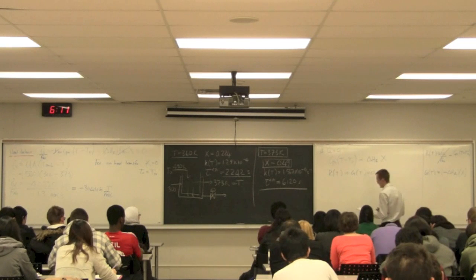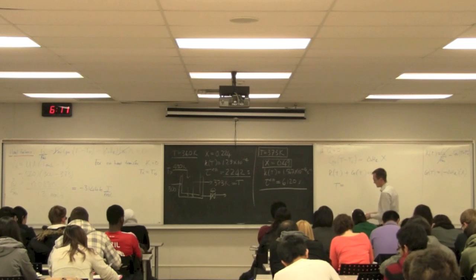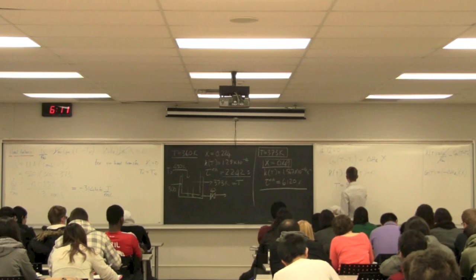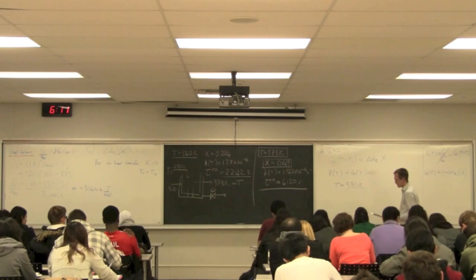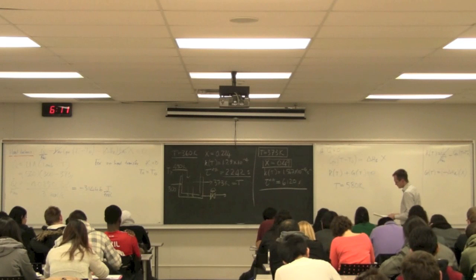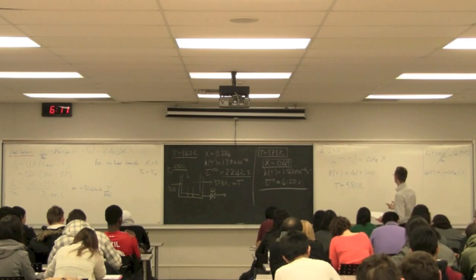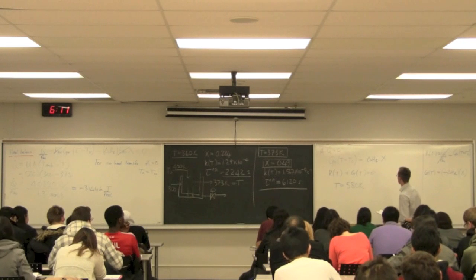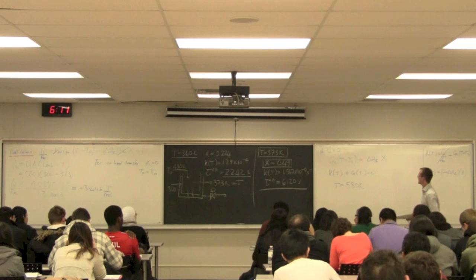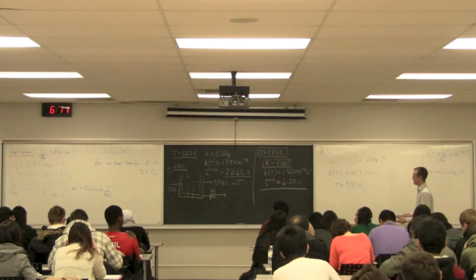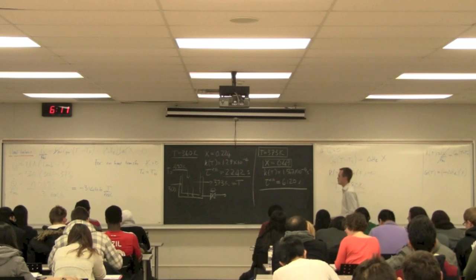What you will find here is that we won't go through it, because again it's a trial and error process. You'll find that the temperature ramps up quite dramatically to 580 Kelvin. I forgot to record the conversion when I was doing this, so I don't actually know what happens to the conversion at the top, but it's quite easy to calculate from this equation here. Okay, so it's guess and check. And you'll find that it ramps up to be a very hot system, 580 Kelvin, much warmer than that inlet.